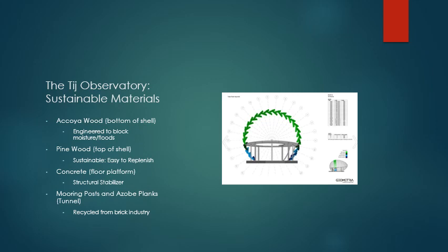The floor of the egg was made of concrete and CLT. CLT is cross-laminated timber. It is used for its strength, because it's a number of crosswise glued slats placed at right angles to each other. This creates stability, and the concrete also creates stability for the structure.